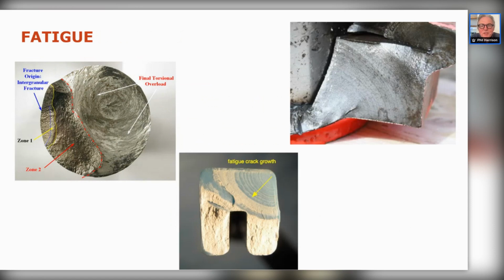And these are briefly some others. You can see where the cracks grow. You can distinctly see the striations in the material. You can also see the final failure, which is rough. The final failure in fatigue cracks, to my knowledge, I have to say that because there might be some technical paper somewhere which says against this, but to my knowledge is always ductile failure.